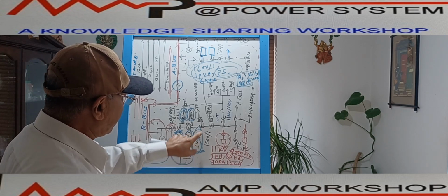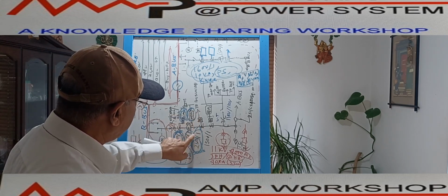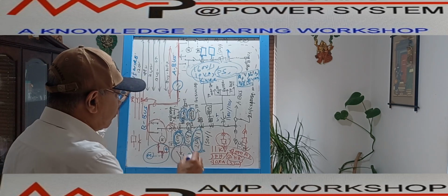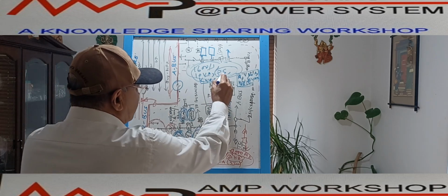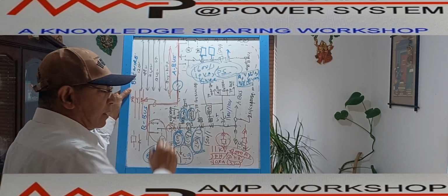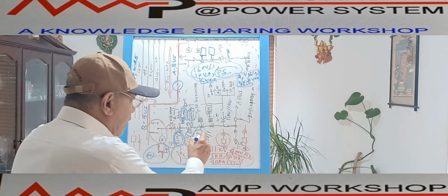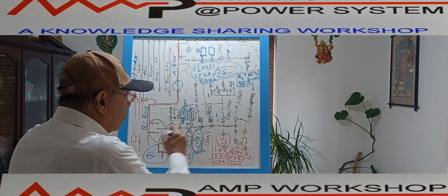So all these parameters will come under the busbar differential CD. When we put the busbar differential CD over here, what will the ratio be? 2000 by 5, we have considered. Suppose the VA is 20 VA, protection class PS class CD, and the knee point voltage suppose 100 volt. That we have to write down over here. The knee point voltage, all this will come over here.